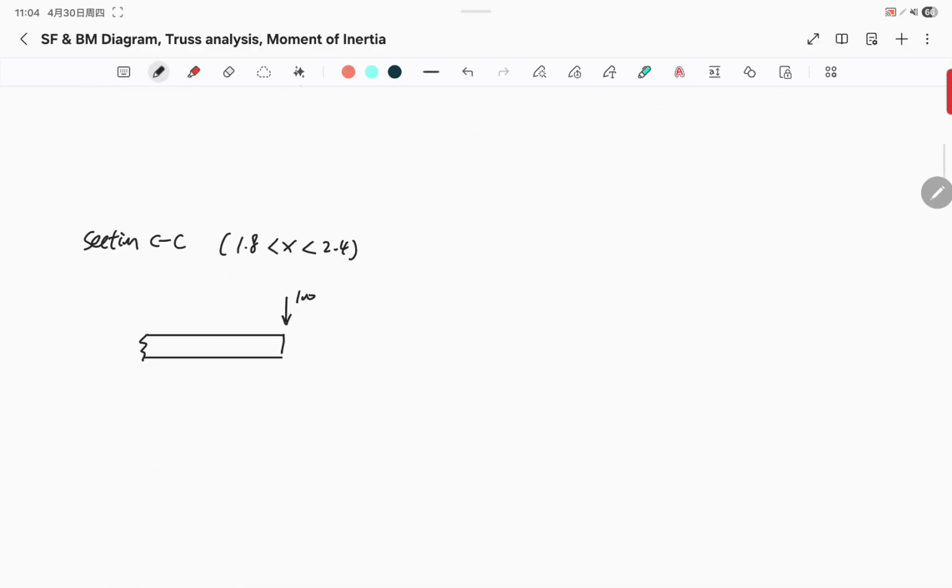Now, what's important to know is that right now the arrows V and bending moment M, these two vectors, we are putting them to the other side. So we're going to flip their directions. V, if you draw V here, it was down, and bending moment is counterclockwise. Now we're going to flip the direction. So V is upward, M is clockwise.